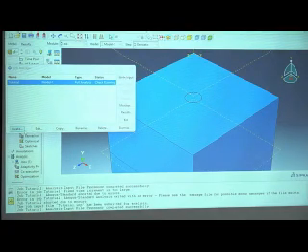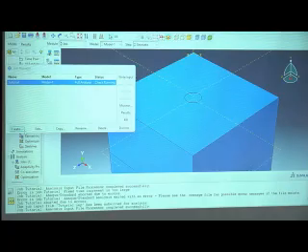What all the input files you created, see if all the data is consistent or not. It's not completing that. Whether your input file and the soil interface, you created the master and slave surface, right? Is the length of the pile and the size of the hole correct? Yes, exactly. It's 1 meter diameter and 5 meter pile. And the hole is also 5 meters. Yes, sir. There's something wrong. Even this, if this doesn't run, surely may not have done.